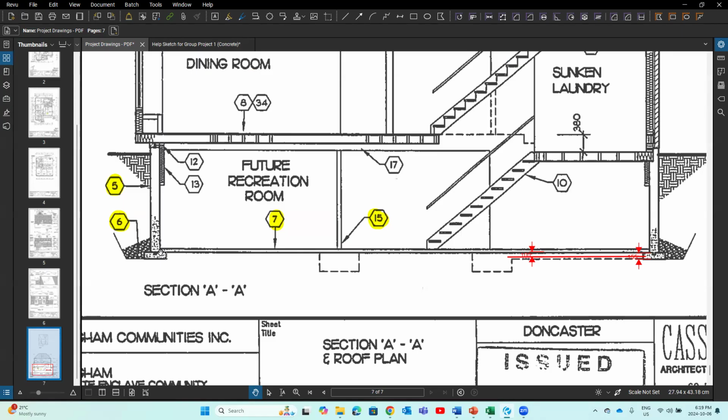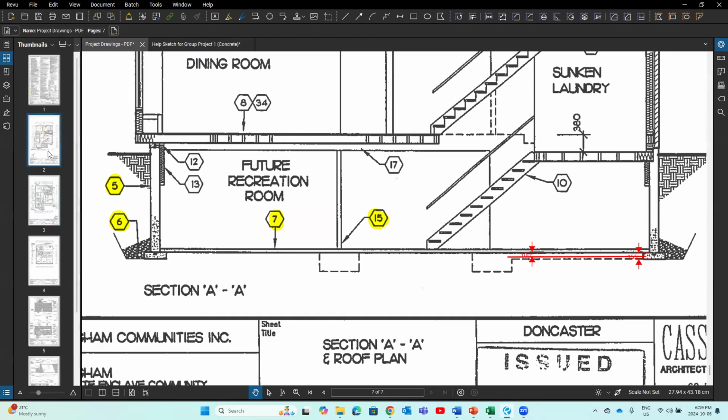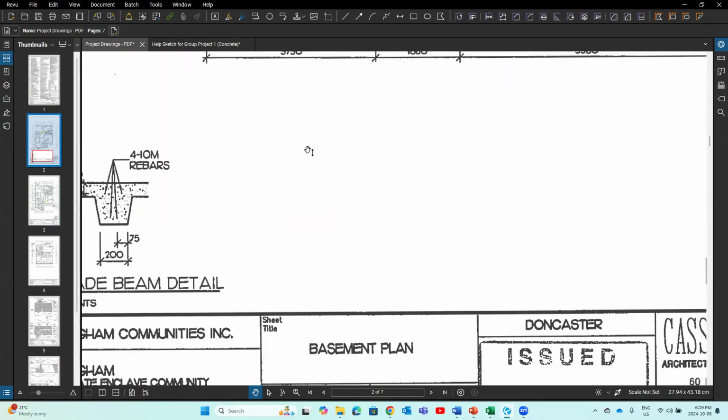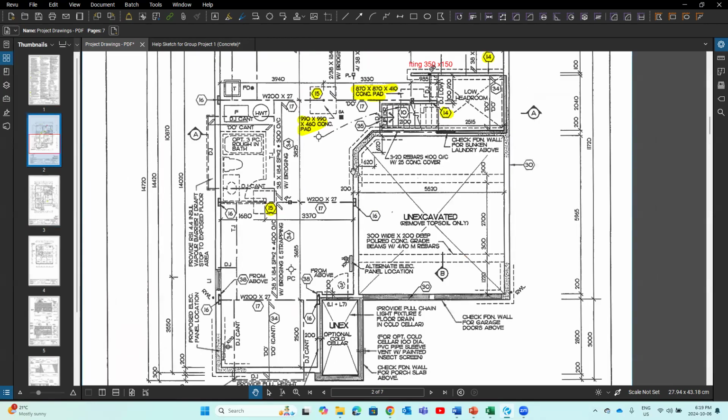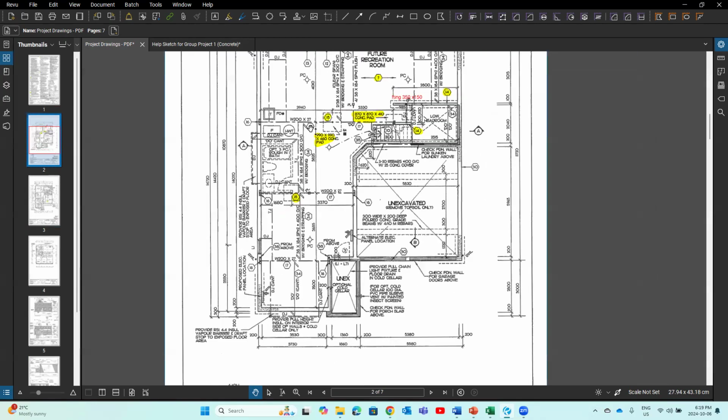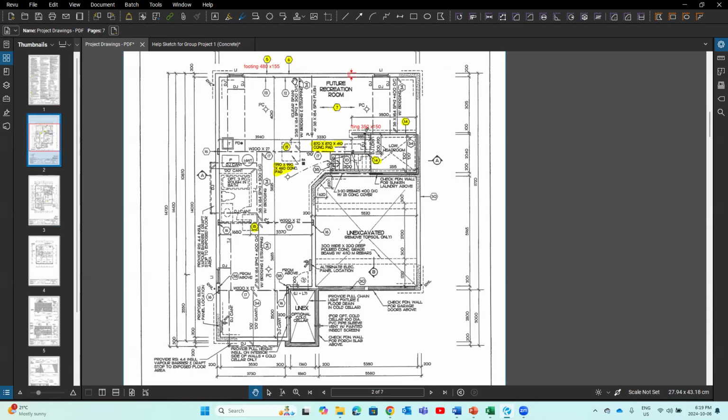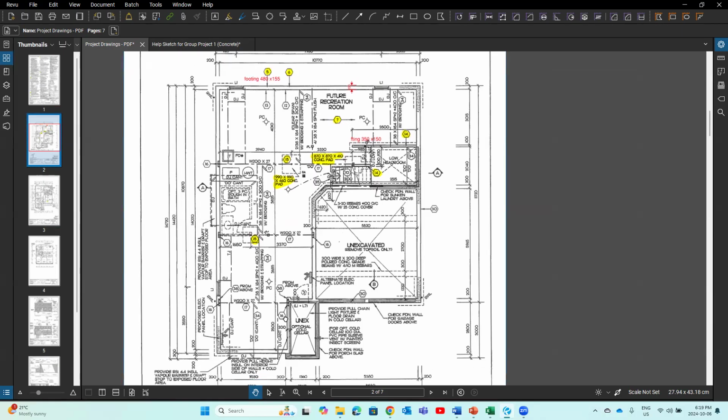The perimeter of a concrete slab, or the perimeter of the inside of the foundation wall. So if we look at the foundation plan, we calculate the perimeter of, say, the inside surface of the foundation wall or edge of the concrete slab.